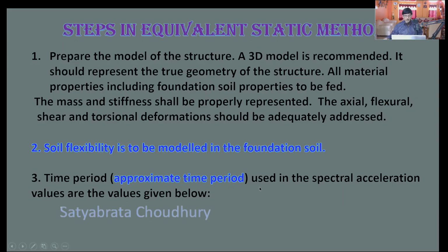For time period, the approximate time period is used in the spectral acceleration values, given below. So for the equivalent static method, you need not carry out the dynamic analysis to capture the time periods in different modes. However, a preliminary dynamic analysis is required to know the mode shapes, how they are playing. The first two mode shapes should be translational along the two main perpendicular directions of the building, and the third mode may be torsional. So for that purpose, a basic modal analysis will be required, and you have to watch the mode shapes for the first three modes at least.